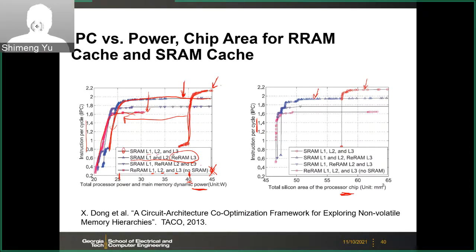if you want to know something quantitative, like 10%, 20% degradation, then you have to run this kind of simulation. Of course, as I discussed earlier, the initial assumption of using RRAM is not very good because of the endurance issue. But you can imagine if we change this to STT-MRAM or SOT-MRAM, as we will discuss later in more detail, this might be some interesting problem or application to look at.